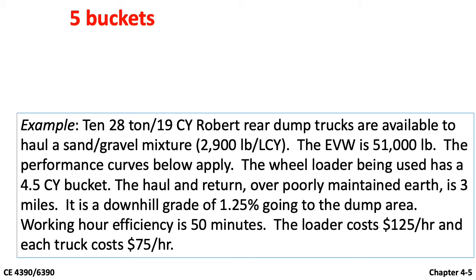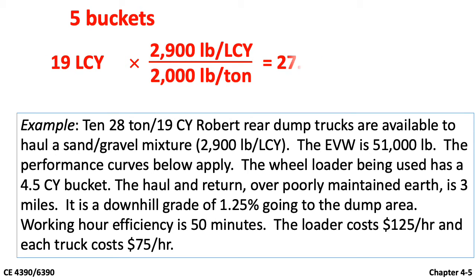So with 5 buckets, the truck volume is 19 loose cubic yards. You do the same process and you get 27.6 tons. So it is less than the given rated capacity of 28 tons, so it is okay.